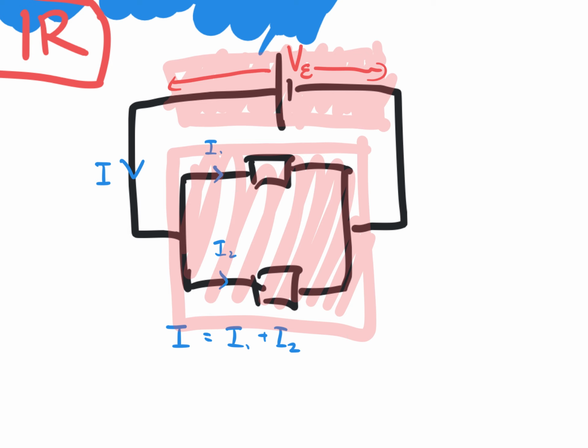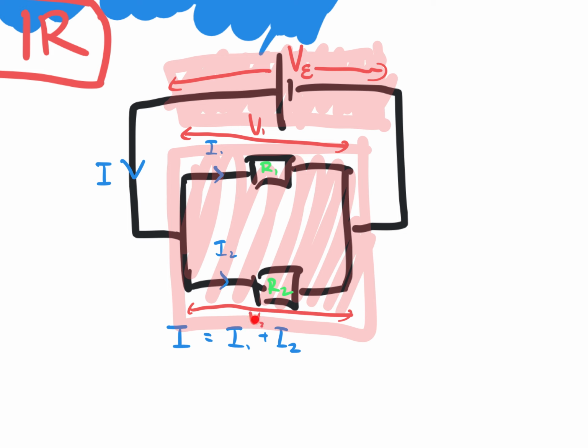So what I do know, like we went through in class, is that the potential difference across this one over here, let's label it so that we can say it more carefully. This is R1, this is R2. The potential difference across R1, which is V1, because it's in that same block, correct? This block, right? Everything within this column, so to speak, will be the same. Which means over here, V2, V1 will be the same as V2. The potential difference across these two points is the same as these two points, right?